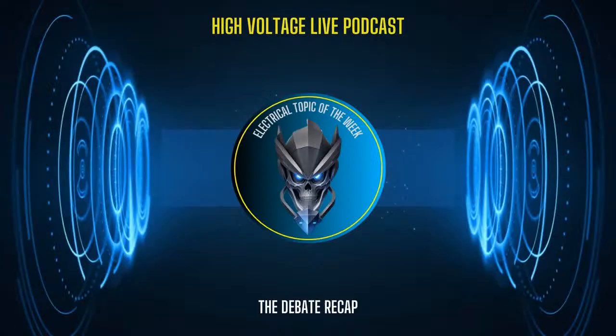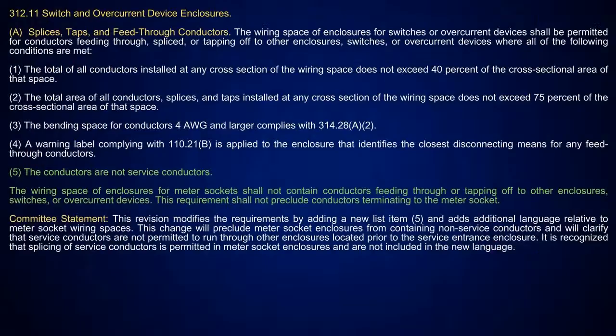Well, does that have anything to do with fused or unfused? Well, yeah, it would, because it's still a meter socket enclosure. Regardless, everything that's said here is talking about the wiring space enclosure for those meter sockets, and it's telling you what cannot be in those meter sockets. I think this helps clarify to make sure there are no other conductors in there.